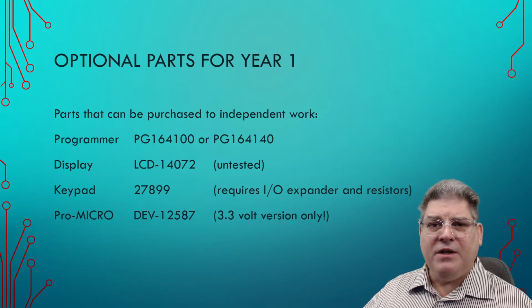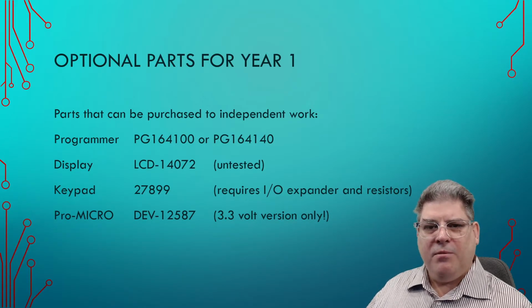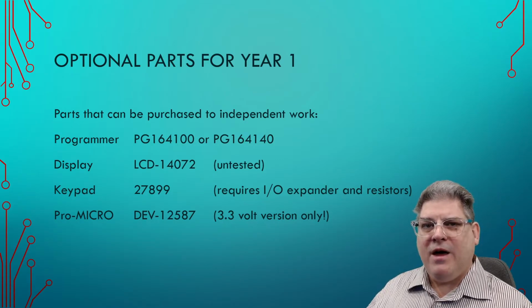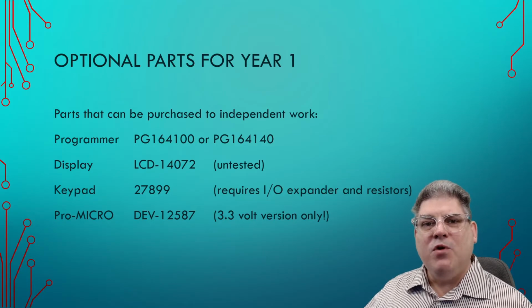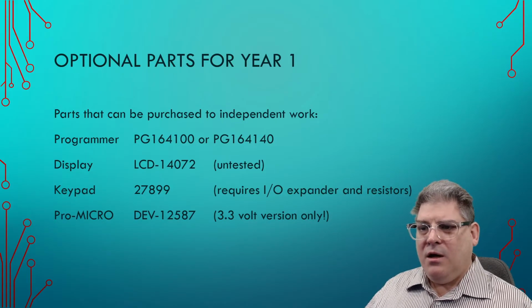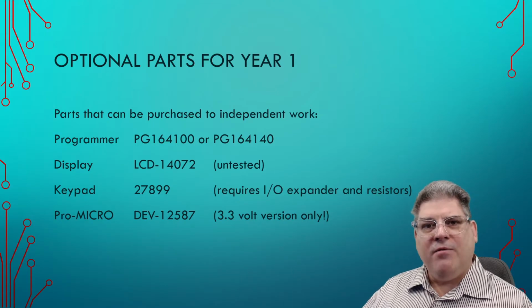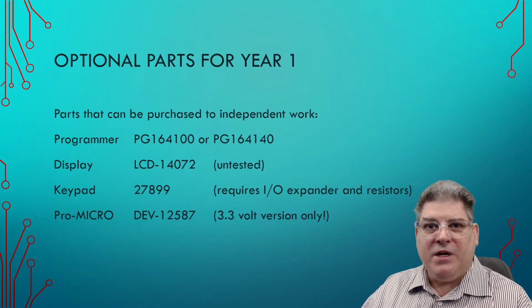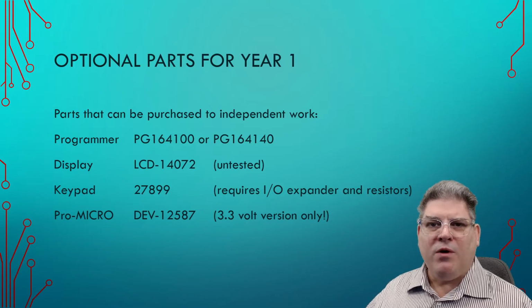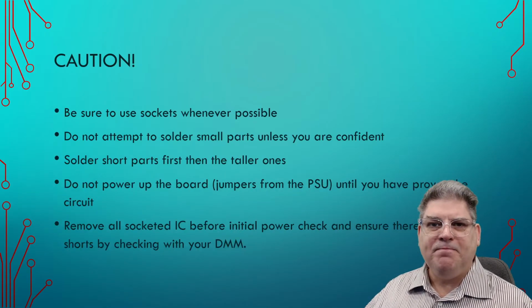The Pro Micro is another feature that you could pop in if you're familiar with programming it in the Arduino IDE. You can absolutely grab that, toss it in. Make sure that you remove the microprocessor chip, the PIC, from the board when you're running the Pro Micro, so the pins don't end up fighting each other. If you happen to have one program to do something and the other program to do something else, you could end up with a conflict that you could damage one or both of the devices.